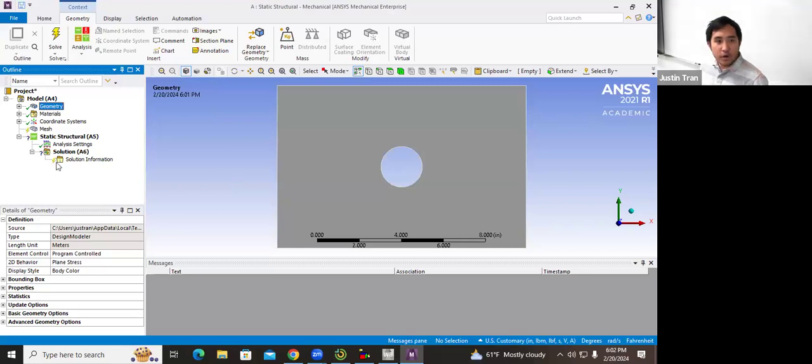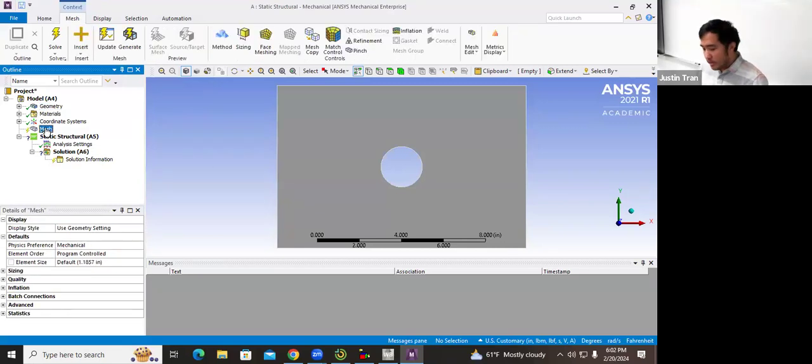Okay, all right. So let's go ahead and continue here. The next step is called meshing. Because what we have right here is our geometry. This is traditionally what you would see if you made a part like this in SolidWorks, that it's all one material. But one thing that you've seen over the last few weeks is that, in order to run a finite element simulation or do a finite element calculation, you need to have elements, right? Otherwise, there's no FEA to be done. And so the process of creating elements for an arbitrary geometry like this is called meshing.